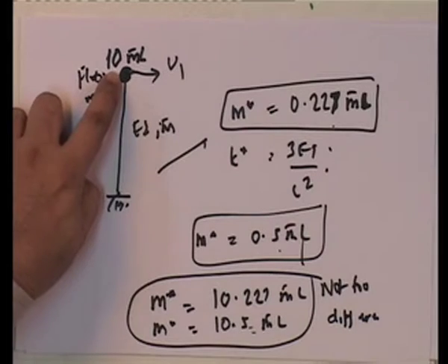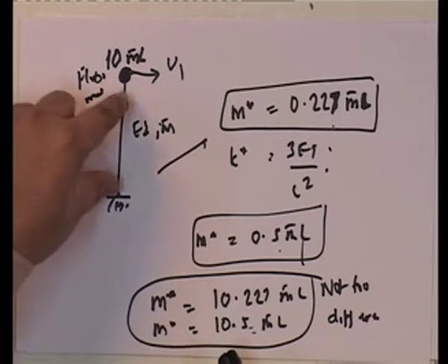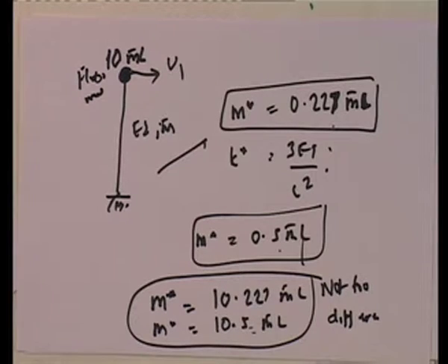And this is the floor mass, because the member mass is now very small compared to the floor mass, which is what happens in typical frame buildings. The floor weights that you have are significantly larger than the member weights, always. Which is why in gravity loads, you pretty much always consider the weight that comes from the floors as part of the gravity load. If you add up all the floor weights, you will see that the floor loads are almost the reaction. So, this one does not look ridiculous.